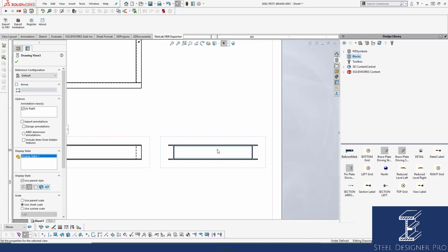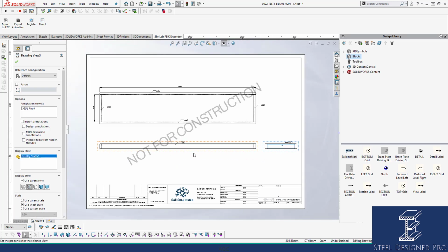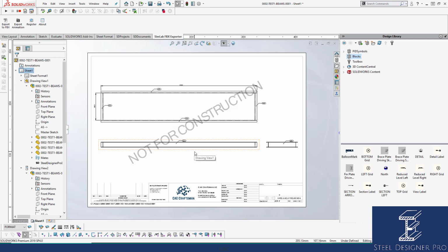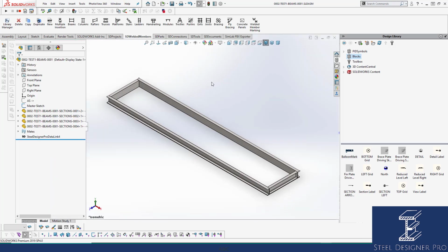and likewise there. Now you can put notes on this drawing by putting notes in the sheet template so that all of your welded members have a welding note. So when we go to the drawing side and you do the batch sheet template swap out from the library model template, which is what we've got in place here, we can then swap that out. Notes can be added to the drawing to indicate what the mark is and where the mark has to be and its position inside the frame. But at the moment I'm just going to do a basic one so you can see what happens when we consolidate.